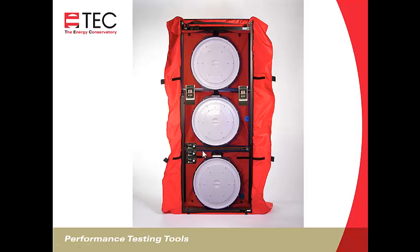And then we added the three speed controllers: the bottom controller for the bottom fan, middle controller, middle fan, top controller, top fan. Instead of using flow rings typically in a test, we'll use open fan, and as fan pressures get low, we'll click one off. So it's very helpful if the top controller goes to the top fan, if it's the top fan you want to turn off, because the software needs to keep track of that; it needs to know which one you turned off. So that's a pretty simple way to allow you to do that.